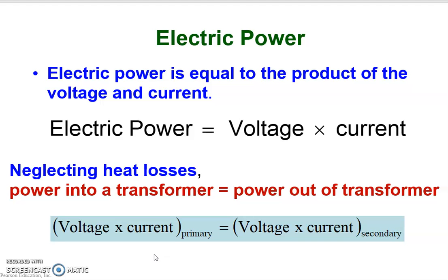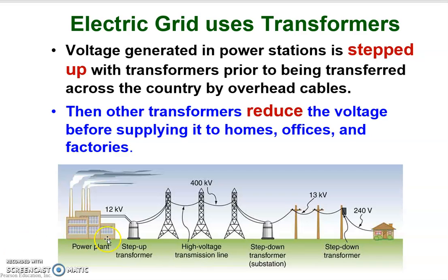So what you are doing is that from a power plant, you will produce an induced voltage. And you can see here it is only about 12 kilovolts. Now, when you transmit, you have to boost that to a very high voltage, from 12 to 400 kilovolts.